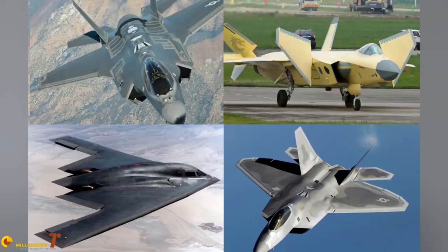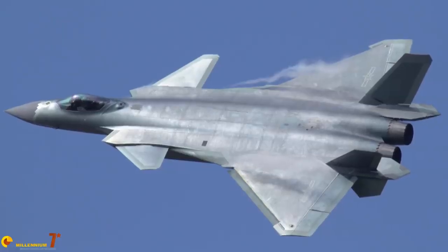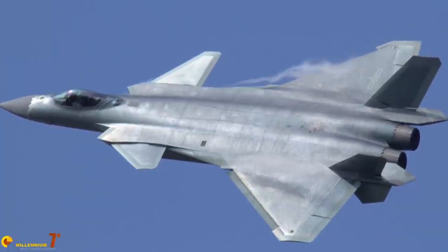Another methodology, more complex, is to make, for example, the entire leading edge of radar absorbing material and then hide a metal structure with no discontinuities, or with a sawtooth as well, under the radar absorbing material, but this is obviously structurally more taxing for the aircraft design. Actually, the two methodologies are often combined, so on the same plane you find the resistive strips and inserts of radar absorbing materials or parts made of radar absorbing materials, depending on the kind of optimization that the designers do.